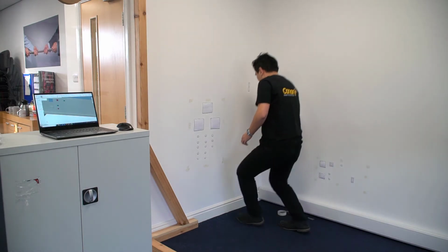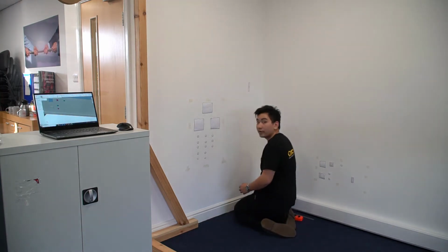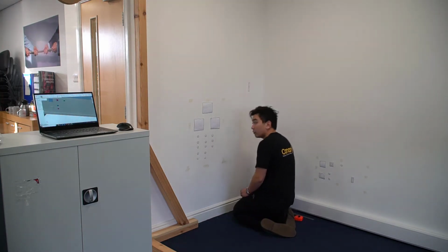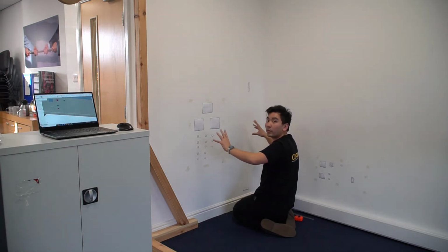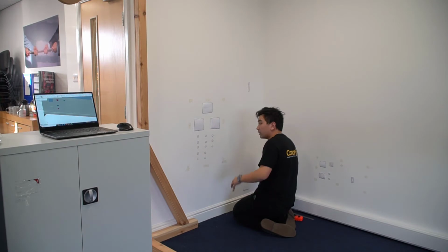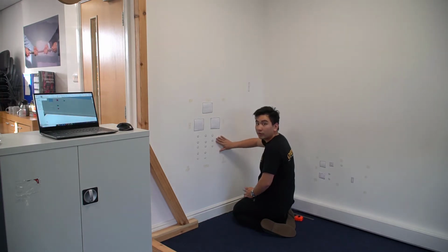I can look at the postures which I have to adopt in order to access it. So this could be one posture, or alternatively they could use this posture. But by having the human machine interfaces laid out around you in a dimensionally correct manner, you can test things like this and capture the postures. And you can also use it as a tool to make recommendations, so you can move these switches and buttons around and make recommendations based on that.